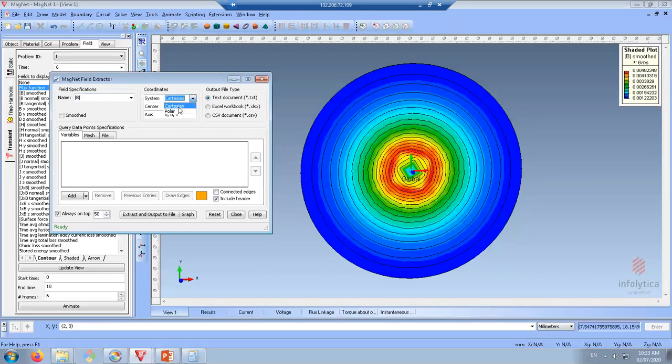We can actually use Cartesian or polar system. Let's use, for example, the first option. Add the coordinate, the first coordinate. We're gonna start from 0 up to the last point of this device, which was, if I'm not wrong, 10 millimeters, right? The outer radius of the airbox.